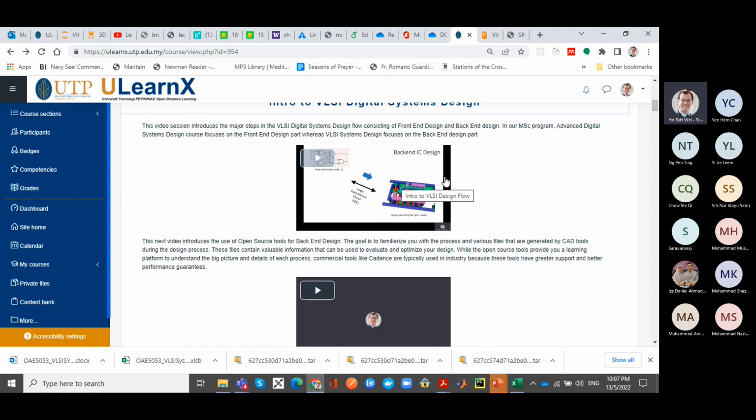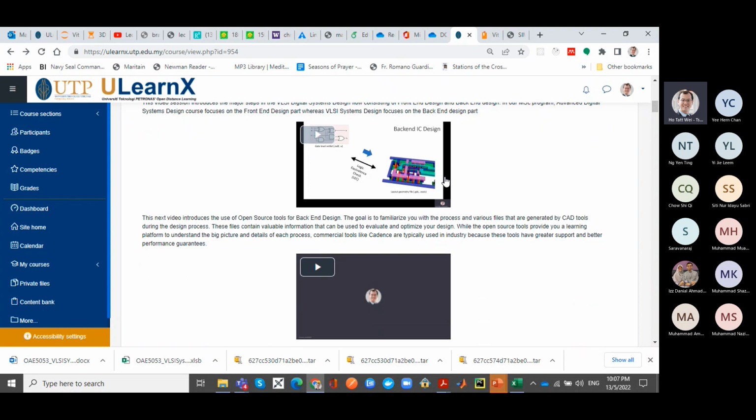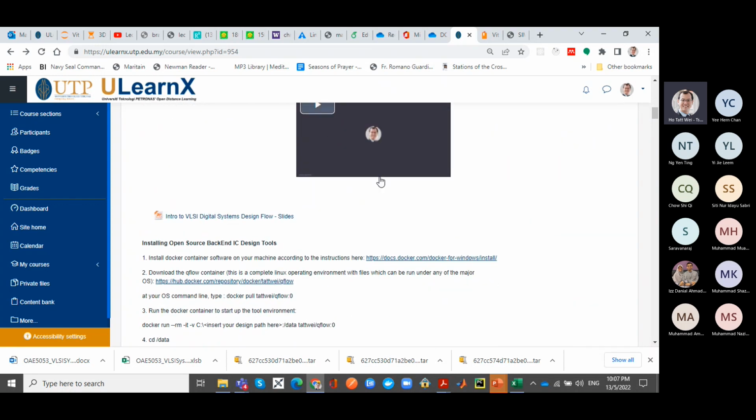So it's just like after your design, your RTL is done, your Verilog coding, your design is done. This course will actually cover how that is translated to the actual gates that the fabrication allows you, and then how do you actually estimate the performance? In this case, it's speed. And then how do process variations and aging actually degrade that? That's the focus of this course. So these are just flows.